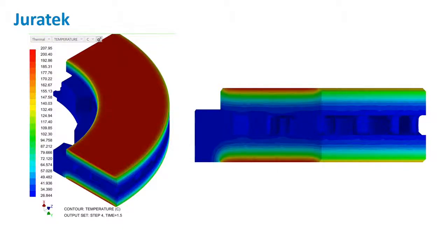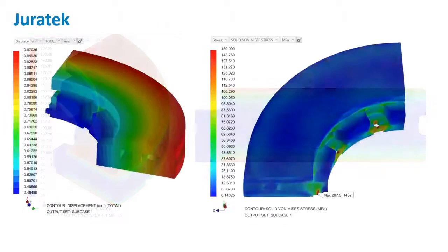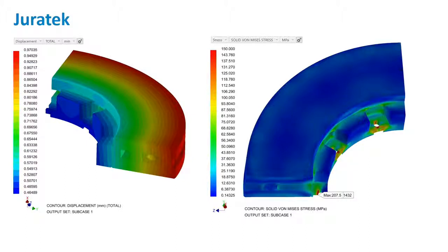And that transient simulation is done inside Nastran. In this case, you get the temperature distribution that you can watch and look if it's realistic, if it's too warm, and then you might need to redesign it, make it a little bit heavier to handle the energy. And then you take it to the next step. Lift the temperature results into the stress solver, put it as a load, the temperature load, and then you make a FEA simulation. You get the displacement and you get the stresses. And from that you can evaluate if it will last or not.